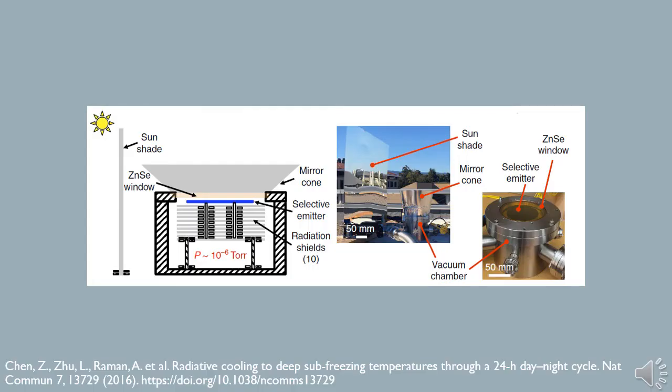The field of radiative cooling has been researched for over a decade at this point. The most notable advances in this field have been research and development of selective emitters, which are black body emitters that emit and absorb radiation mainly inside the atmospheric window, thus allowing radiative cooling to occur while placed under direct sunlight. A team at Stanford has used such materials and a vacuum chamber to reach 42 degrees Celsius below ambient temperature using the displayed design.